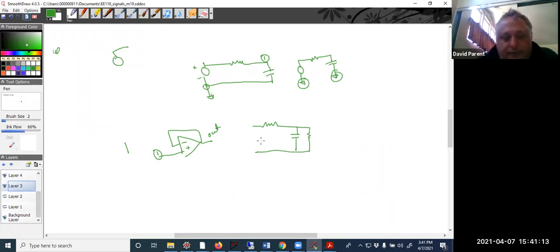So if you want to find the natural response of a system, you short voltage supplies. So if this is an input, I short it. And then if I wanted to see what would happen, I would put an initial condition on this capacitor, and then it would decay. Now, I have a node here. I can go through this resistance to get to that node. I can go through the capacitor to get to that node. I can go through here to get that node.